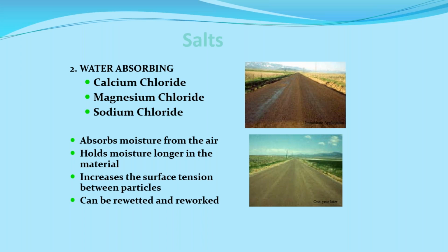Make sure you have a specification. The DOT has specifications for every one of these chemicals, and you need to be aware of what those specifications say. What's the concentration? Like I said, magnesium chloride comes as a liquid. And normally it's around about a 32, maybe you'll get up to 33, 34% concentration of magnesium chloride versus the water.